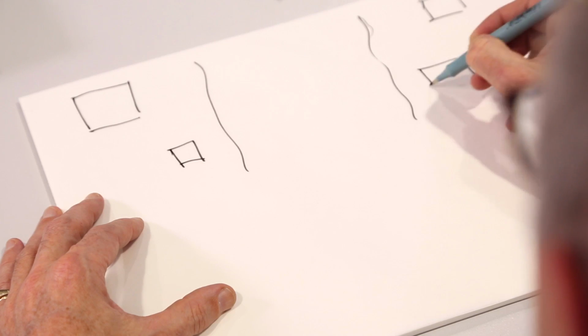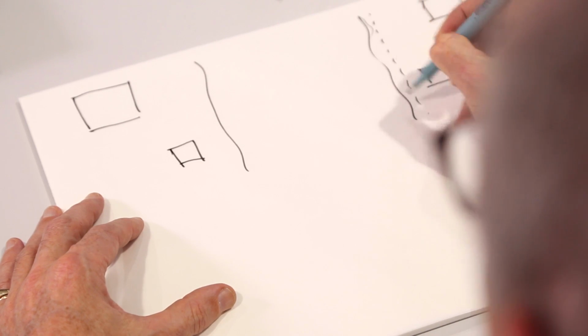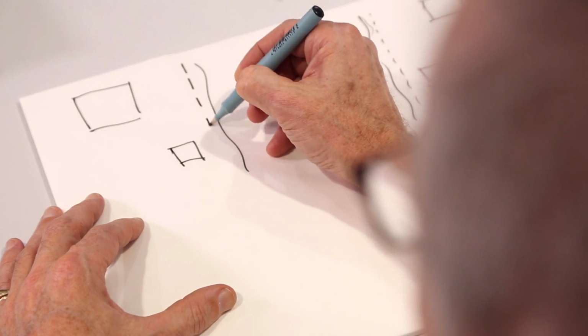This time, we're going to look at the structural aspects. How does the structural engineer go about creating a structure which is going to satisfy all the various constraints? For me, I always start with the long section through the bridge centerline. I find that the most valuable thing to do is actually to draw a plan with, if it's a river, let's say, the key features on it. Maybe there's a footpath along one side and there's a railway on the other side, perhaps.